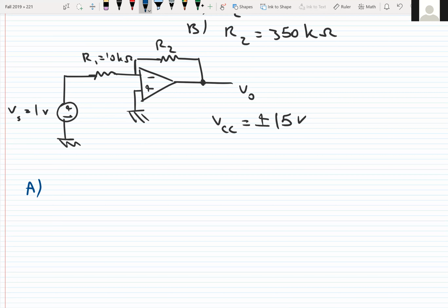The first thing we need to do is solve this circuit like other op amp circuits that we know. VP and VN are here. Of course, VP is known. We know that the value of VP is equal to 0, which is equal to Vn. So Vp is equal to Vn is equal to 0. And now we write KCL for the node which connects the input to the output, which is here.